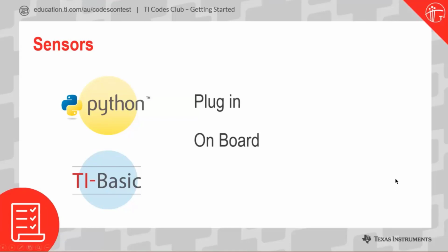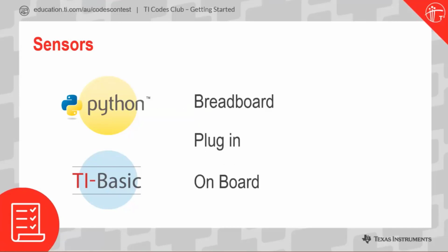However, if you want to go one step further, on the front of your TI-Innovator hub, there's also some breadboard inputs and outputs. There's 10 of them which you can specify as being a combination of analog, digital inputs or outputs. So we're going to set one up as an output, but we're also going to set one up as an input. I kind of need to do both because I'm going to use the Innovator hub to supply some power to a sensor and then get information back from that sensor, what it's doing or how it's being manipulated in the outside world.